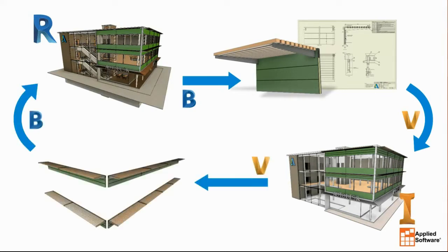When the manufacturing models are positioned and sized correctly, we will see how they can be exported as a native Revit or BIM neutral IFC file for further coordination and review. Most importantly, we will see how any changes made to the Revit project file will update inside Autodesk Inventor to save time on model updates and help us keep the design and manufacturing details in sync.